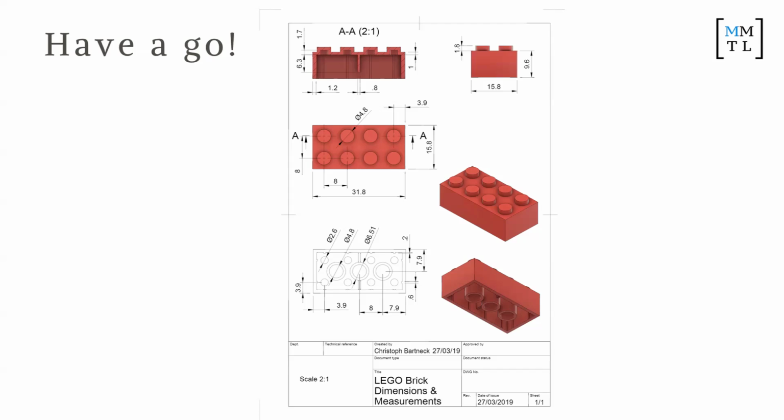So I want to... You can just cut it again, you can extrude it again. Is there a way to just move this sketch before the extrusion? Oh, you can, yes, you can. So you just need to make a new sketch, because it's currently on it. Cancel. Just make a random sketch in the 2D model, then just finish sketch. Anywhere, yeah. And now you should be able to match the previous. Or finish the sketch.